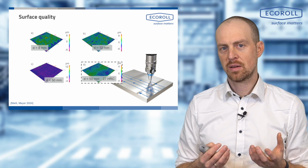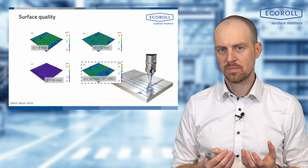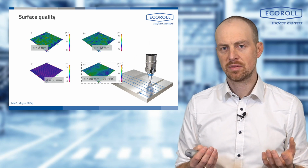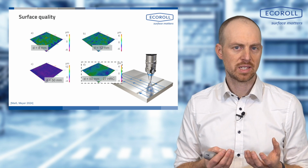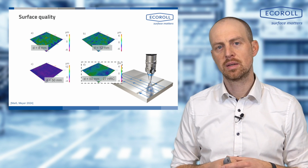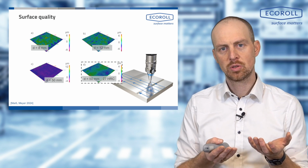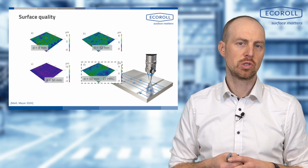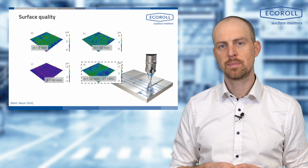Sometimes, when hammering, you might even intentionally aim to achieve a specific texture. There are various research studies that investigate different ways and whether I can structure this hammerhead. Can I attach any pins to this hammerhead that penetrate deeper into the surface, so that I achieve a basic smoothing, but can also imprint so-called lubrication pockets into the surface? This would also be possible with hammering.